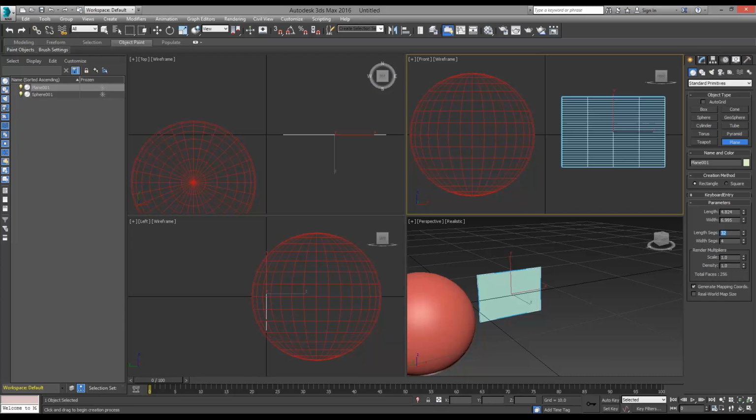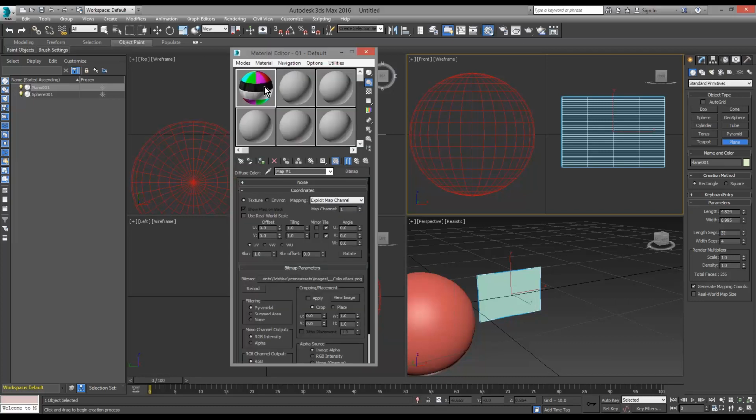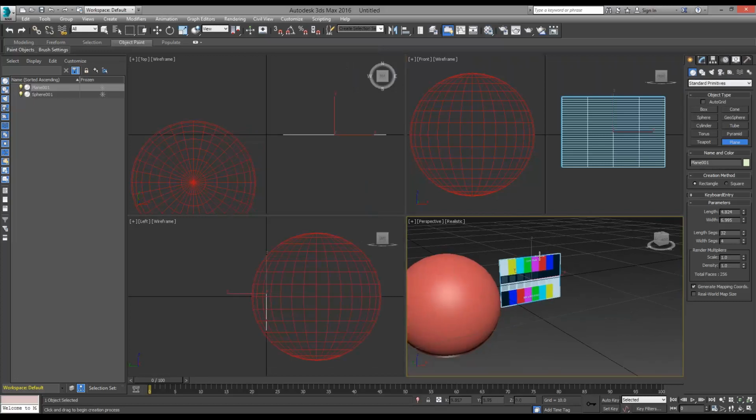But if I set it up to 32, the shaded result, if I put a material on it, is not changing because it's just a planar surface. So having a lot of segments in here doesn't really give you any advantage. It's just eating up your performance.